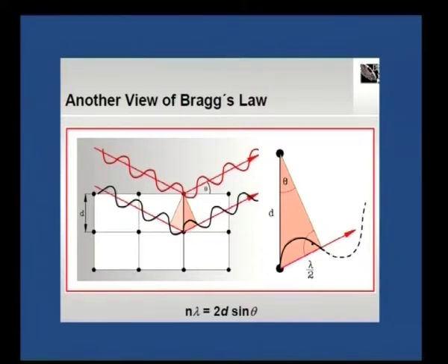This combined with a, the lattice constant. Apart from that, the hkl, we will be seeing in the next chapter, the chapter on crystal structure, more about hkl, the Miller indices used to define a crystalline plane. If you know hkl as well as d, a can be determined.